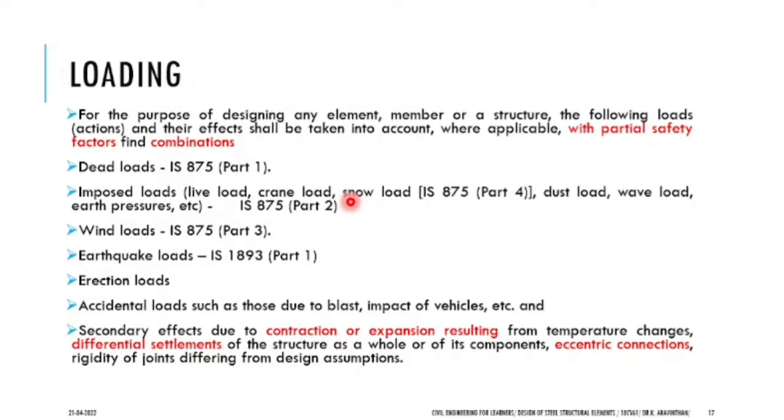When you are designing your structure, you will not take only dead load and live load; you will also be taking floor finish, and taking the total load. Yes or no? When you are designing a slab, what are the factors you will be taking? These 3 factors, no. But if you are designing your building in the northern part of India, you have to consider snow load. A separate code book is given, and what is the thickness of snow? There will be snowfall, and a certain thickness of snow will stick on your roof. The rest will fall off, and you have to consider that snow load. So for that, a separate code book is there, IS 875 part 4.